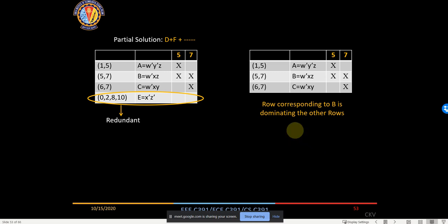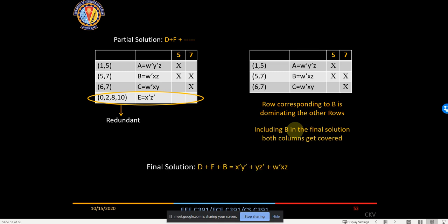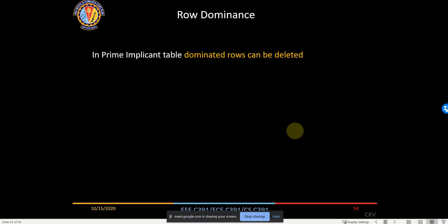So in a full adder, if we implement it using two half adders, the carry delay will be 3. In a ripple carry adder, when we use 4 full adders, the full adder may be implemented using two half adders, or it can be anything. That will be specified in the question. It will be specified whether it is implemented using half adders or not, and that will decide the delay.